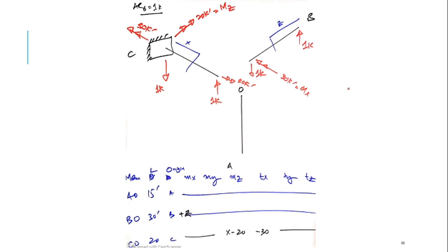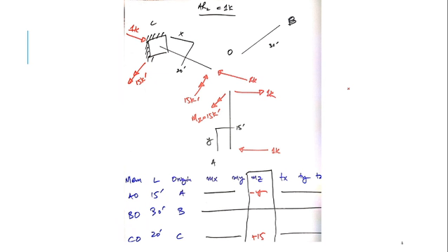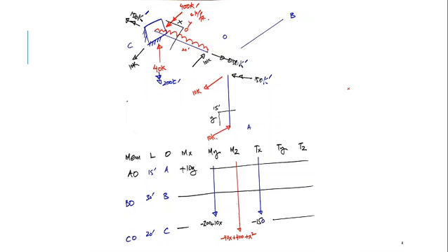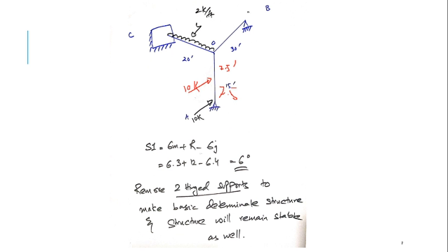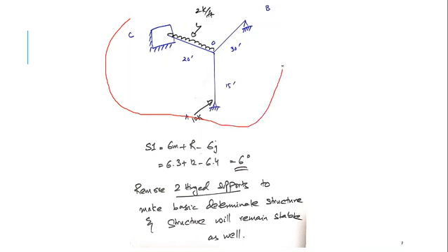Okay, next I have to calculate the DRL matrix. The DRL matrix is actually the displacement in the released structure due to applied loading. So the flexibility matrix has been developed, and this is the frame. The degree of indeterminacy is 6, and it was made determinate by removing these two hinge supports.